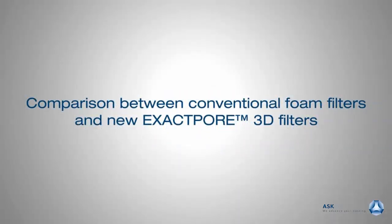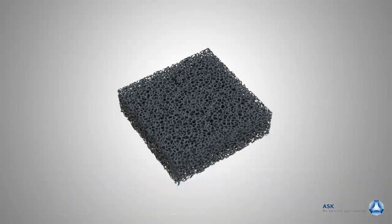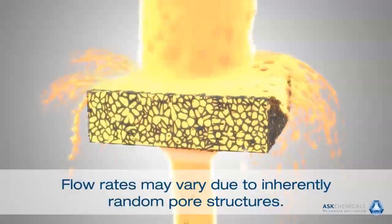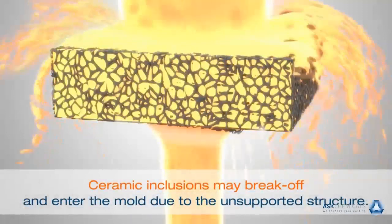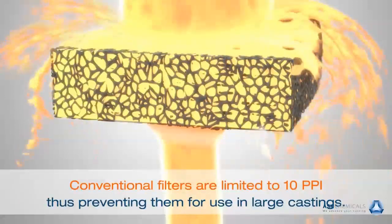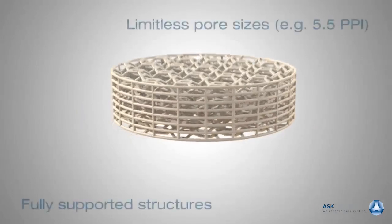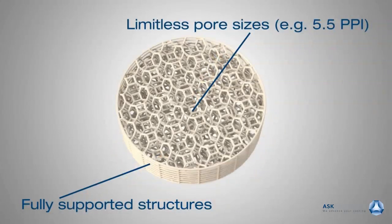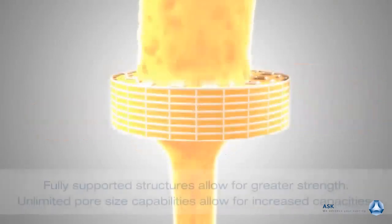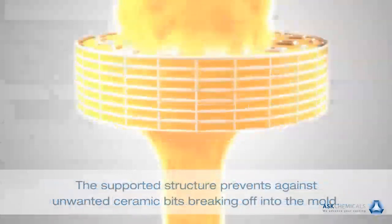When comparing foam filters to the new ASK Exact Pour 3D filter, one can see inconsistency with the foam reticulate pore size. This can lead to variation in flow rate and capacity. Unsupported tendrils are fragile and can be damaged in shipment or mold insertion. This can allow filter bits into the casting cavity. The Exact Pour filter was designed to fully support its filter webs with unlimited cell sizes available. These filters are also offered in many customized shapes and sizes. The fully supported structure allows for greater strength, while increased cell size improves capacity.